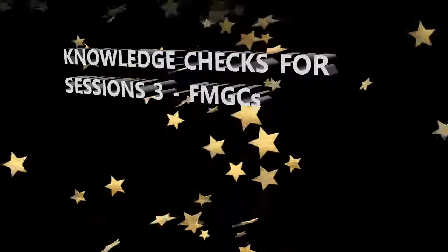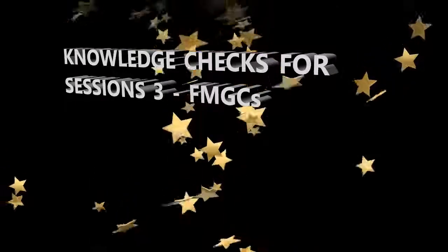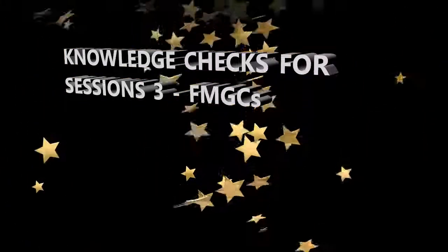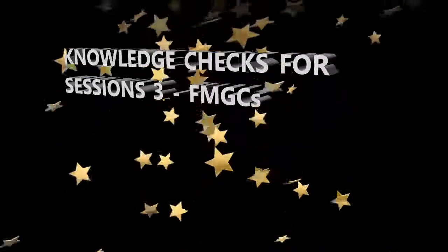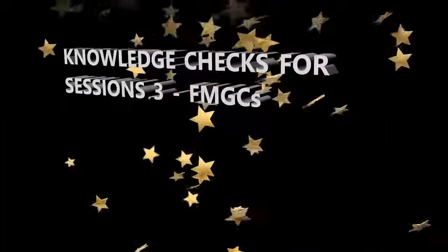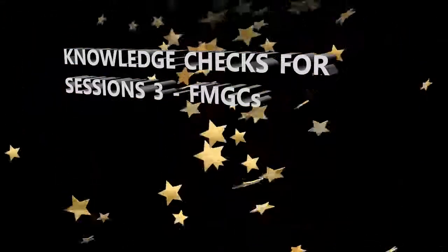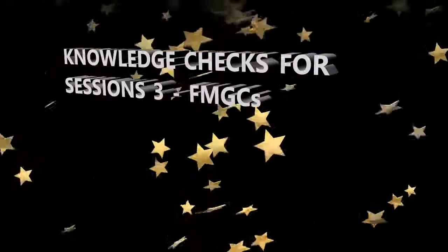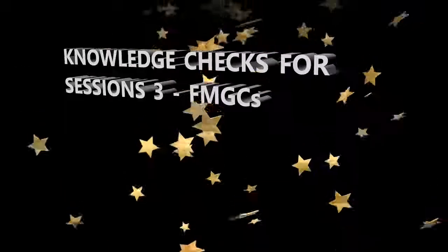All right, last question. Which gives the short-term interface between the crew and the FMGCs? Is it going to be the FCU or the MCDUs? The answer is the FCU, Flight Control Unit. All right, that concludes this whole topic on autoflight systems for the Airbus A320.